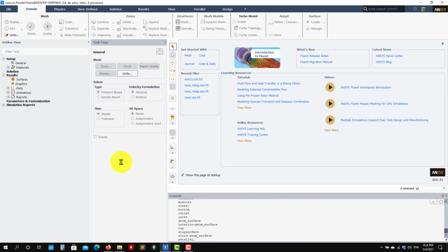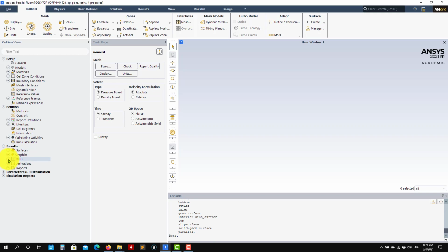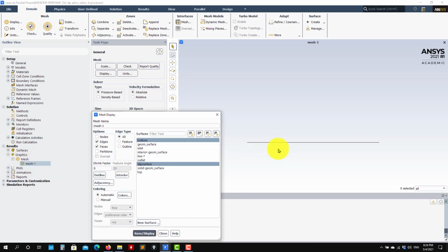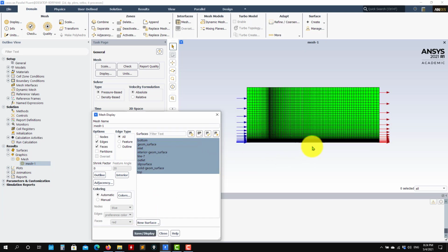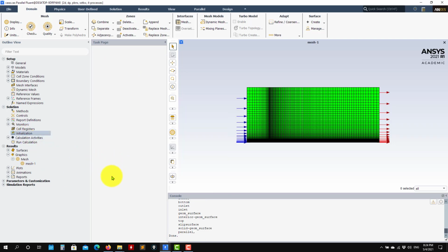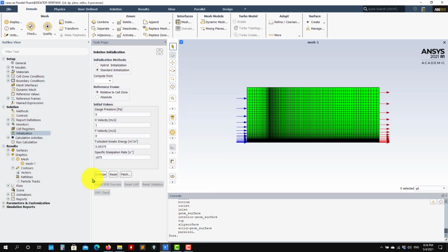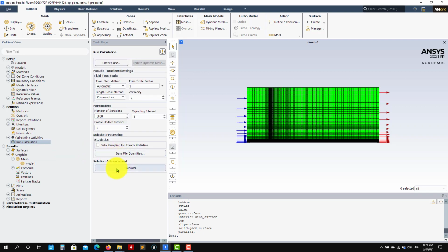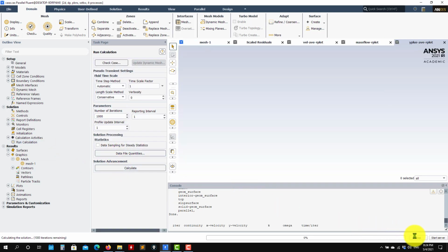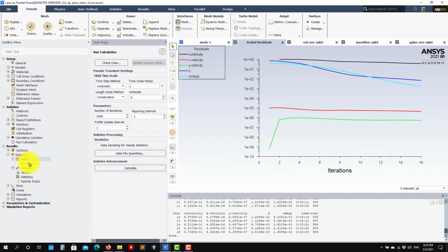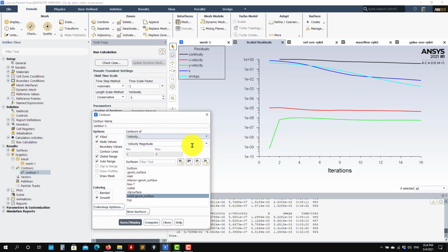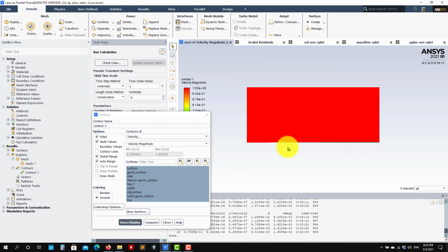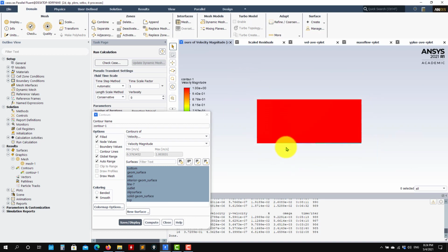So when we read this geometry, see that now if we plot the mesh, okay, we don't have access to that third dimension. You get this. So looking at the values at the wall is a little bit tricky. Let me show you. Okay. So let me run a couple of iterations so you see that. Okay. So if I go here now to post-processing and visualize everything, it's 2D. Okay. It's constrained to this XY plane. Okay. So you cannot rotate.